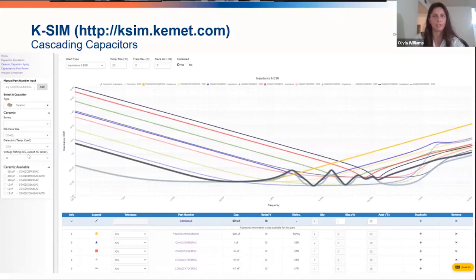So the criteria, I guess if there's a frequency target given in the microprocessor that you're using, that would probably dictate the frequency bounds you're going to look at. So I guess you would target your impedance at those frequencies given, I think is what the question is getting at. If not, please reach out and we'll flesh it out better.